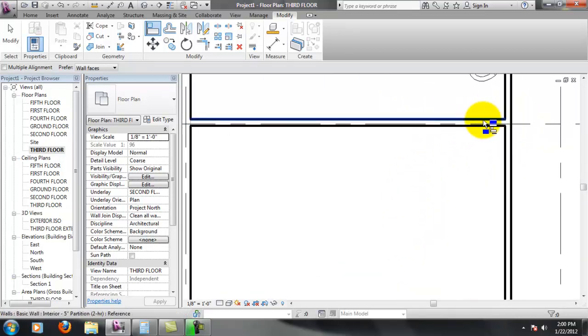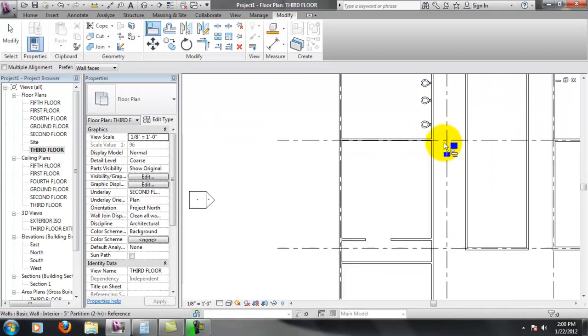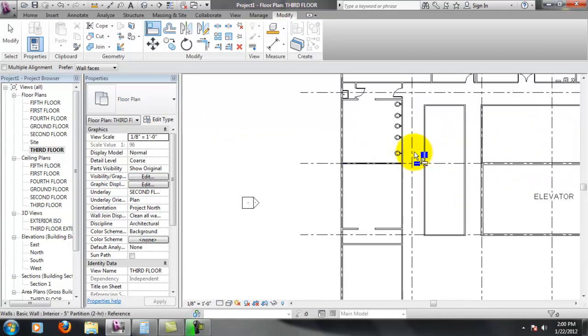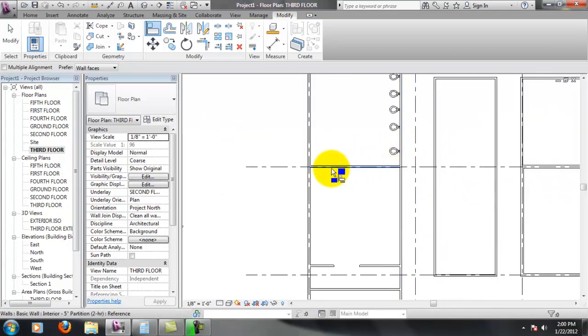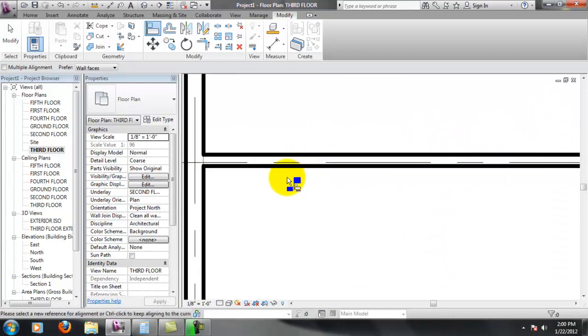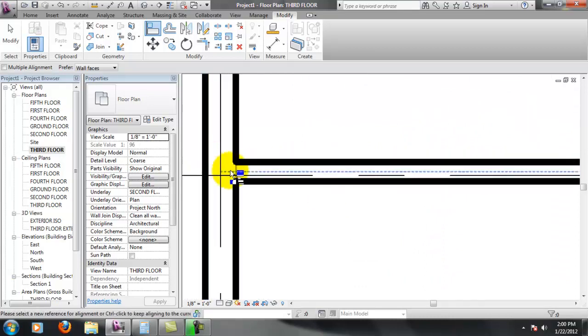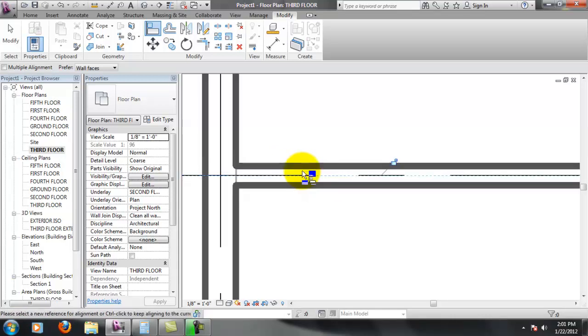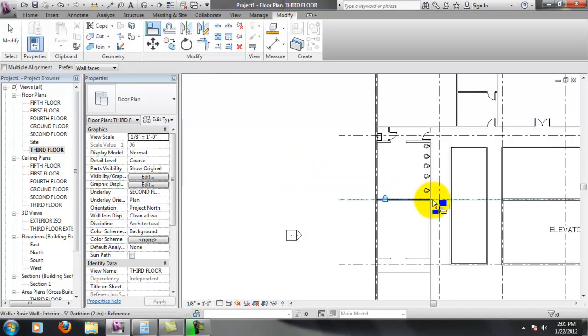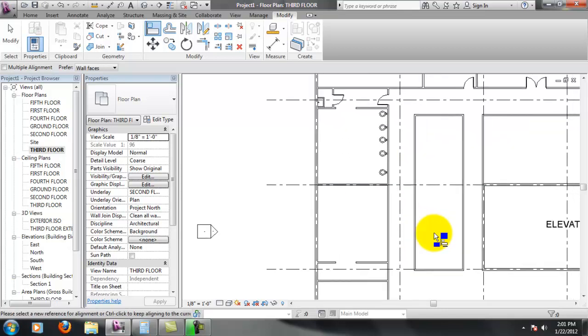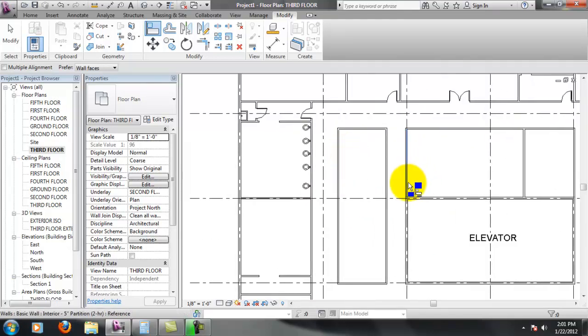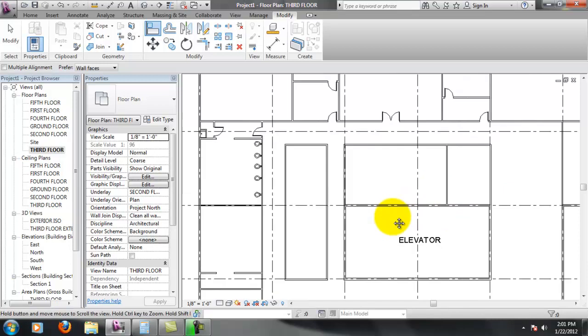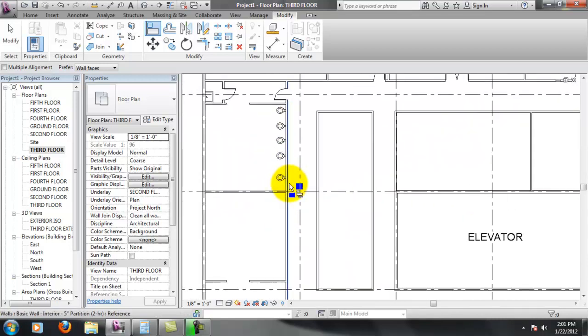And that's actually coming out pretty nice as far as staying on the grid. We could nudge that down a little bit more. You know what? Let's go ahead and do that since it's so close. Construction guys will love you for that. So we want to align to this. I'm going to select the grid line first and then select the center line of the wall and lock that. That'll nudge that down. Now we might have lost a couple inches, but at least on the drawing the dimensions are going to look nice and neat. We're not going to have some weird rounded inch number there.